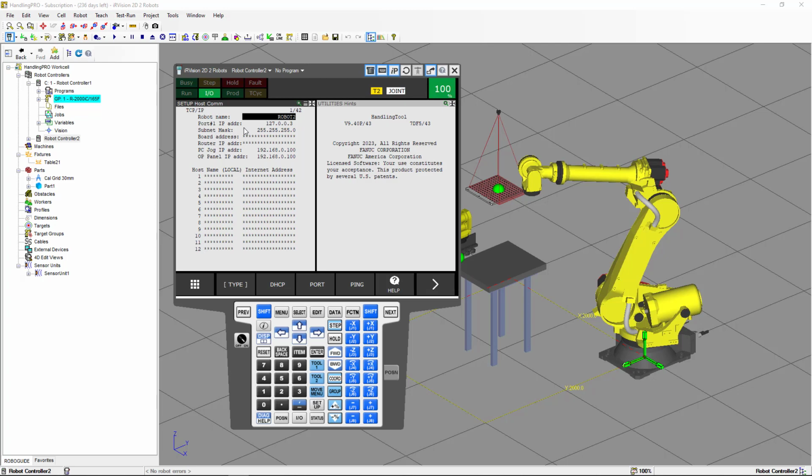And when you set up the cross communication, you want to have a port dedicated just to the communication between the two robots. So in a real situation, you would probably use port number 2. With this, we have the TCP/IP communication configured.